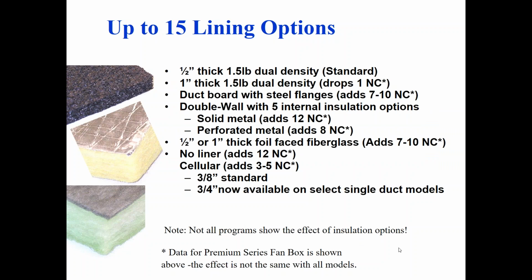All right, there are numerous insulation lining options available on these VAV boxes. By default, almost every VAV box that you would specify or order is going to come with a 1/2 inch thick fiberglass liner. That's going to be the standard on there. That is mainly there for sound purposes.